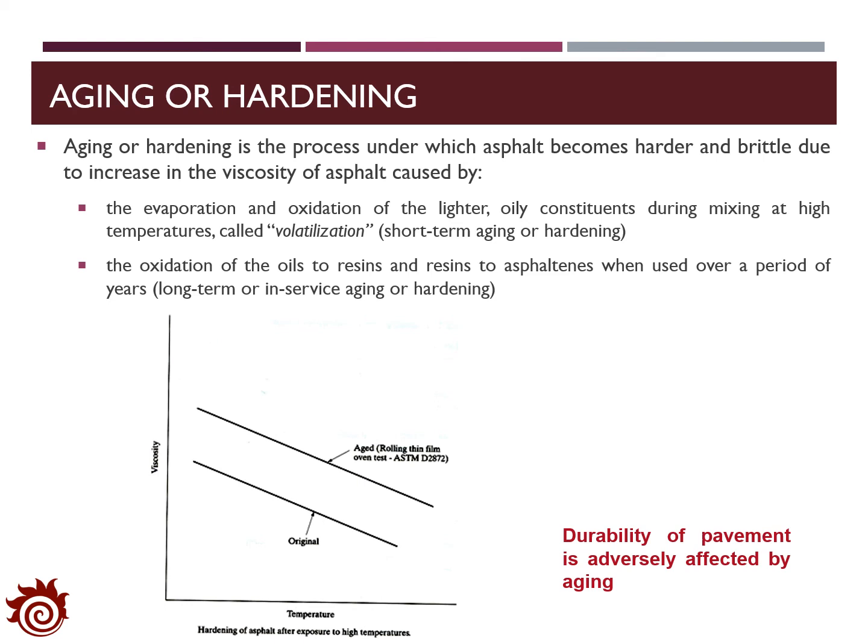The figure below shows the viscosity at different temperatures at 2 different years. We can clearly see that the viscosity of the asphalt cement increases dramatically from the time of construction to several years after construction. In addition, we can see that aging can significantly reduce the durability of the road pavement. In that sense, we have to take aging seriously into consideration in pavement design.